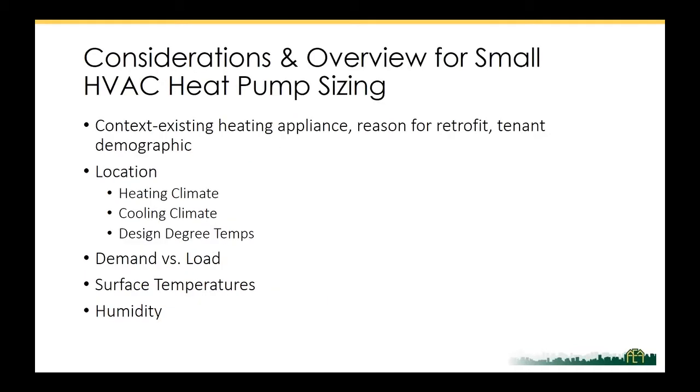All right, considerations and overview for small HVAC heat pump sizing. I believe it's important to understand the context: the existing heating appliance, the reason for the retrofit, the tenant demographic. Is it a single person? Is it a large family? Is it a college student? And then also location. Is it a heating climate? Is it a cooling climate? What are the design degree temperatures?